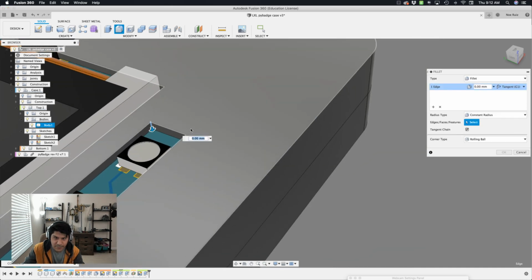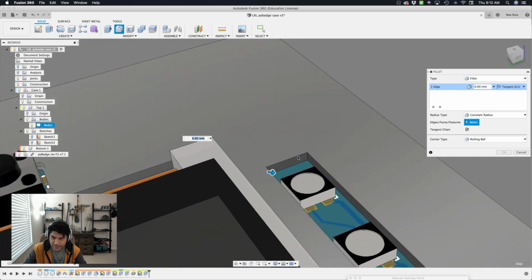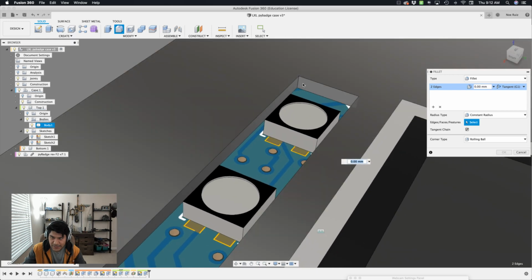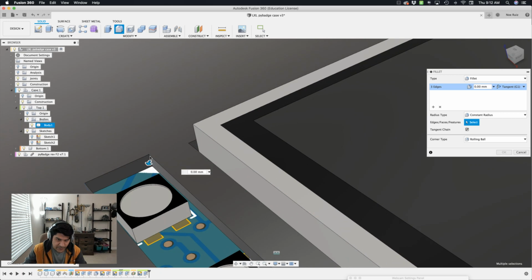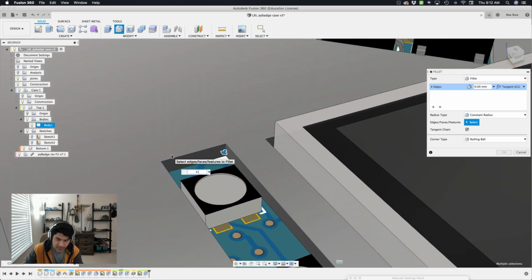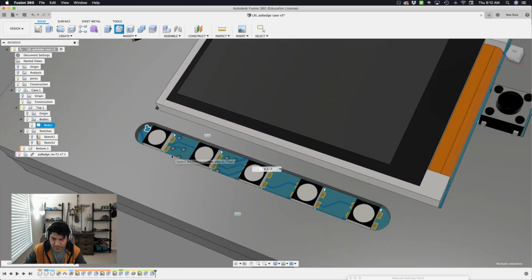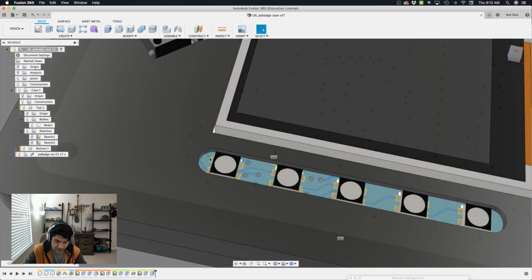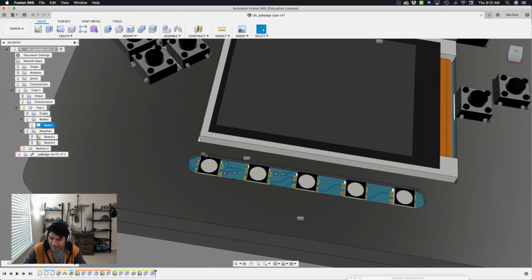and then I can select these guys. The thing won't go away. There we go. Now it goes away. Use your space mouse, and then I'll select these edges here. So the total length of the edge was 4.3. So when you're working with fillets, instead of putting 4.3, when you divide that by 2, it gives us the radius, and now we have a super flush circular fillet. And I'll hit OK. So there you go. So if we didn't have that 2 millimeter distance between these guys, your circle would pretty much cut into this guy here. So that's why it's 2 instead of just gap.